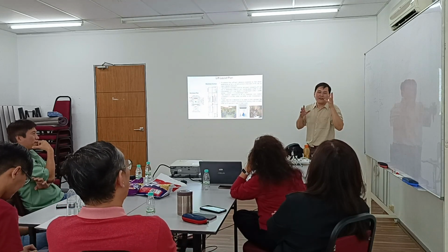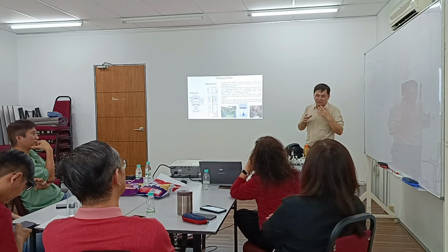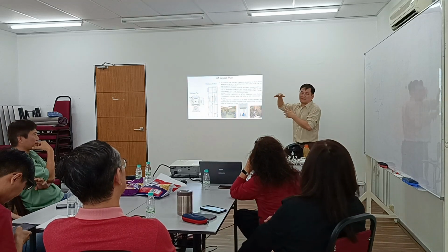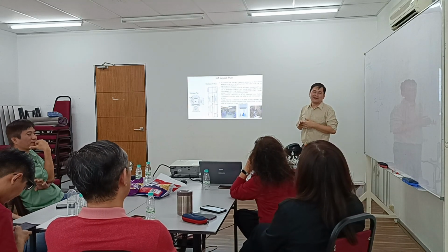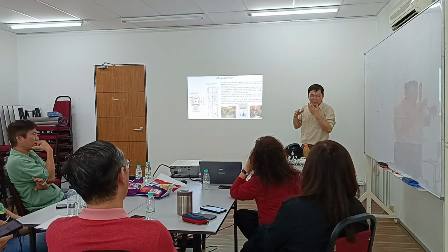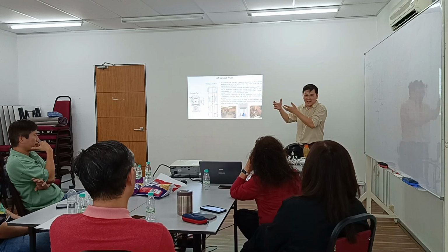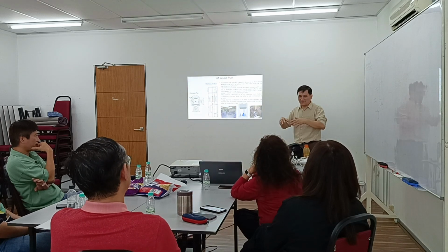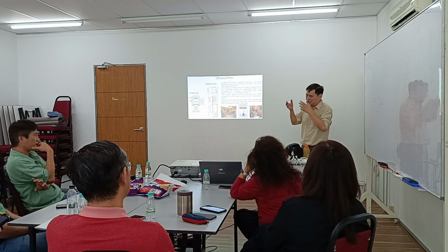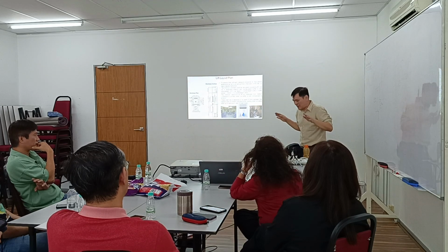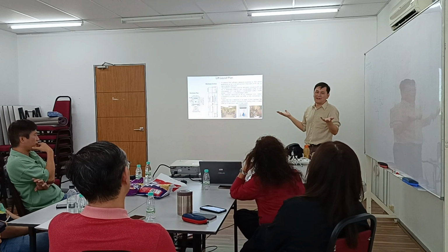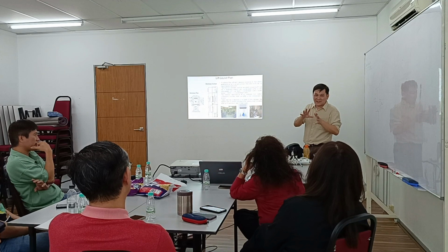But this is actually the very, very worst case. In fact, the roof can hardly break, and before the roof breaks, the safety gear can already be engaged. This is just the very, very last measure. Still have to ensure there is a clearance so people can lie down. So please don't misunderstand that.